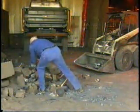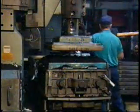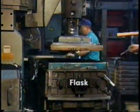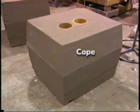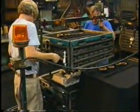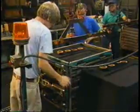Although the molds are expendable, the sand can usually be reconditioned for reuse. Sand molds, made in halves, are built by tightly packing the sand around the pattern in a flask. The upper mold half is called the cope, and the lower half the drag. The mold includes one or more risers, venting provisions, and a system for transferring the molten metal to the mold cavity. This system includes a pouring basin, sprue, runner system, and one or more gates.